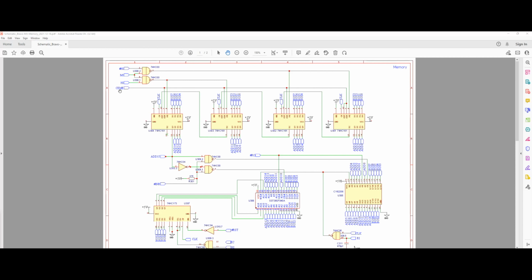And also we have another signal here, as you can see, called CEME. Again, we use the same signal in our program counter. Basically this is count enable in our program counter circuit, and memory enable in here, because obviously this circuit is in our memory, but it's the same signal. This signal goes to pin 7 on our counter chips, and what it does is just enable counting. So as soon as this signal goes high, the whole circuit will start counting from whatever value we have set through the inputs. Now, I guess the input side should be clear by now.